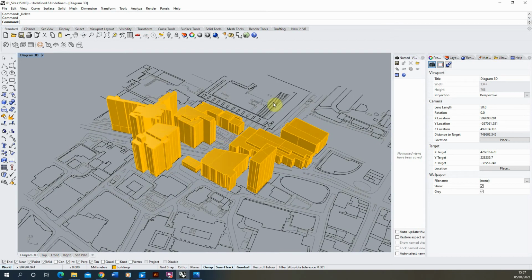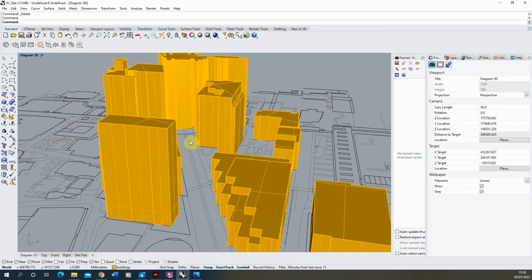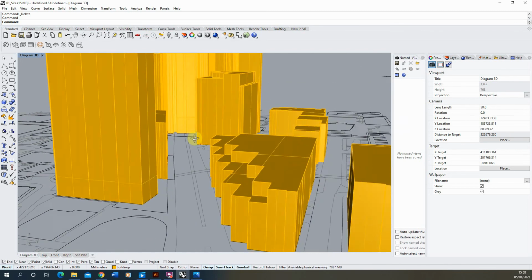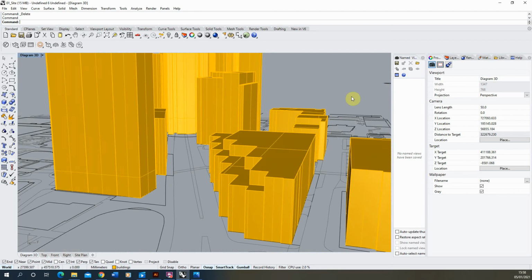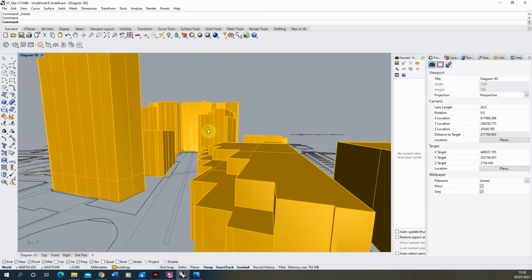Usually to do this, I'll set up what's called a parallel projection in Rhino, which will be a more orthographic or diagrammatic viewpoint to allow me to create my 3D image. By default, Rhino uses a perspective projection, which means it acts as a real camera would, with a focal length and a vanishing point. That can be seen just on this right hand side with nothing selected. In your properties panel, you'll have projection as perspective and it will have a lens length. If you change this lens length, it will change the focal point of the image and how wide the lens is.